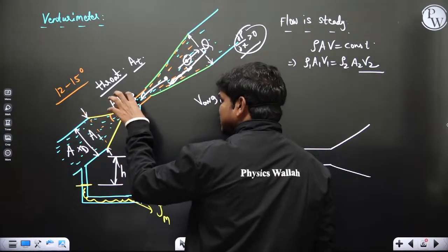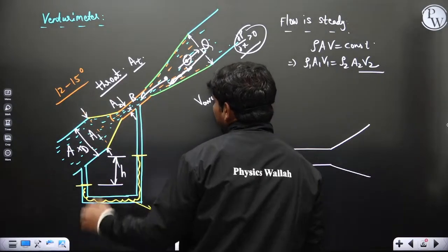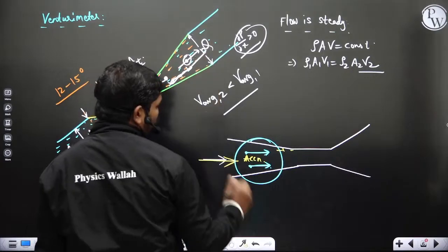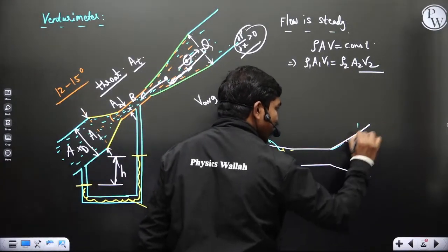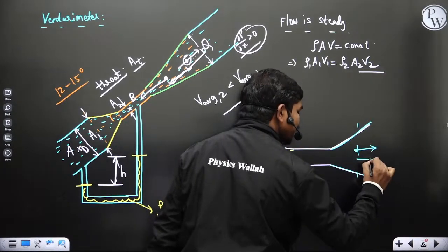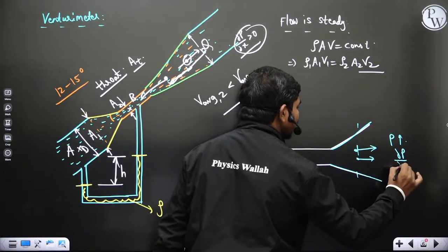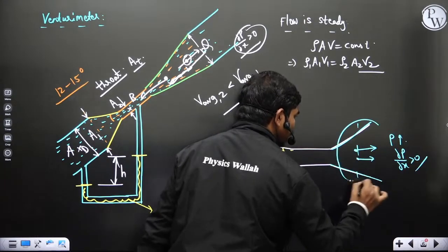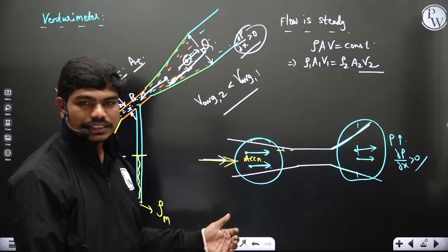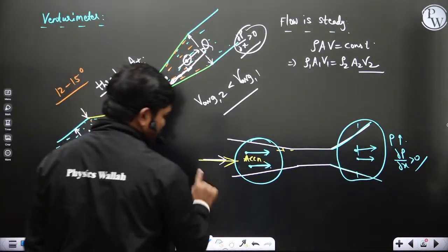So connecting this high cone angle in the upstream direction will actually increase the flow. And secondly, in the downstream direction, whenever the cone angle is high, the fluid decelerates, meaning the particles get slowed down very much, so a pressure increase is possible and adverse pressure gradients could develop in this particular locality. So that's why we generally don't go for this configuration, rather we go for this configuration.